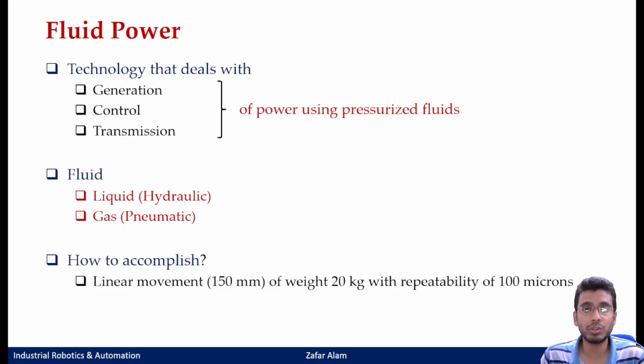So what you actually try to do is see what type of task there is, and then give the best or cheapest alternative for doing that task. If you just go to servo motors, the cost will become very high. If you require a feedback mechanism, then you go for servo motors, or else it will be sufficient to do it with stepper motors, right? So this can be one way of doing this task.